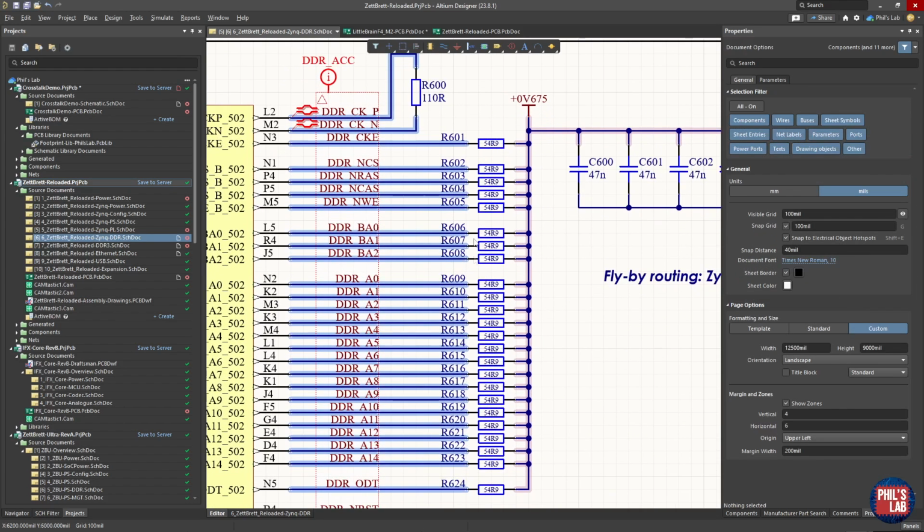We have these single-ended termination resistors of about 55 ohms. We could use 50 ohms because 50 ohms is the characteristic impedance of my traces, of these single-ended traces. So remember, 50 ohms or above to minimize undershoot. So we can go, for example, 10% above to about 55 ohms.